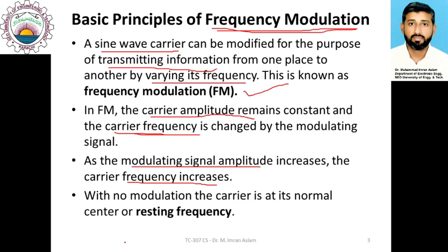And of course, if there is no modulating signal, the carrier will be transmitted at its normal frequency, which is sometimes called the resting frequency. So the resting frequency is the frequency where the carrier is not modulated. So it represents actually the frequency of the carrier.